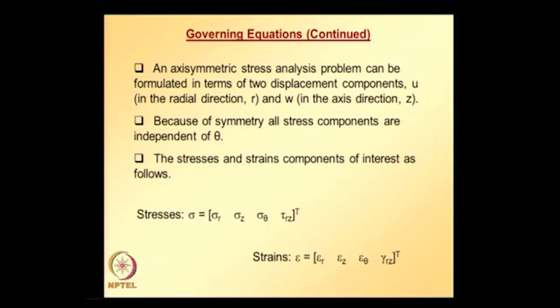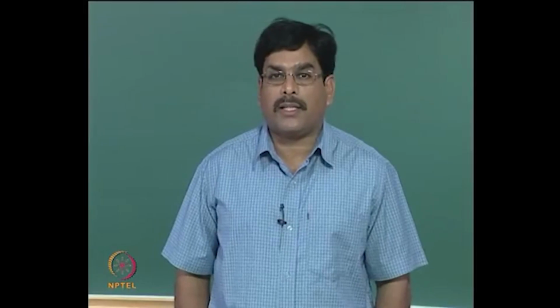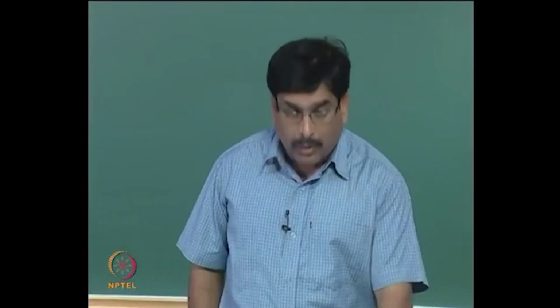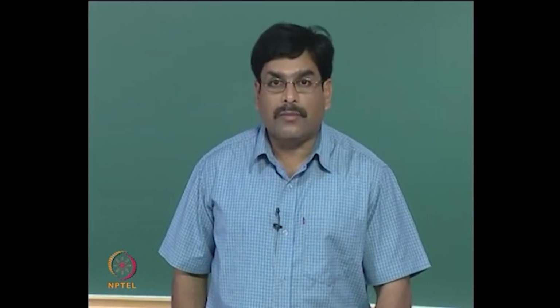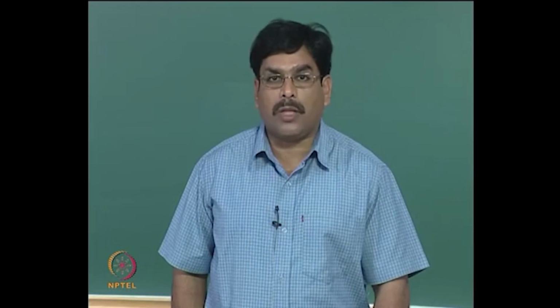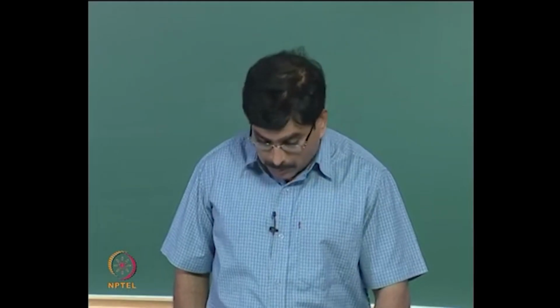So, similar to plane stress, plane strain problems, we first need to identify the non-zero stress components and non-zero strain components, and then we also need to know the relationship between strains and displacements, and how the various stress components are related to the various strain components. We require all these equations to develop the finite element equations based on the potential energy functional, similar to what we did for plane stress, plane strain problems.